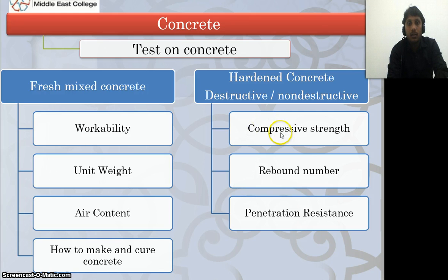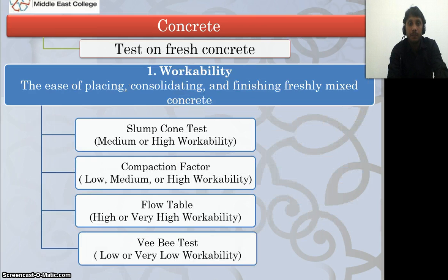These are the tests which we can do for hardened concrete after 28 days, 3 days, 7 days of curing: compressive strength, rebound number test, and penetration resistance test. So you will be studying deeply about these tests in your later subjects or later modules.